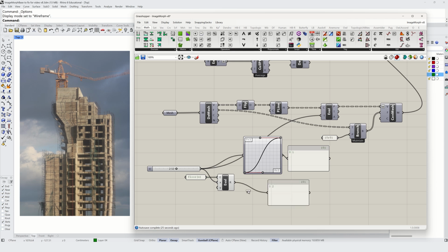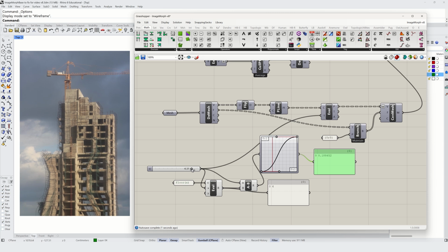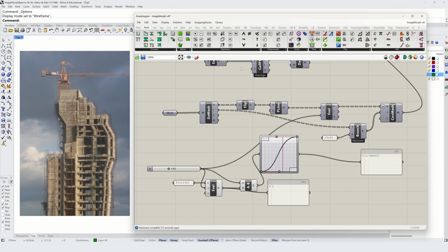Subtract this from the slider to isolate the decimal portion and feed that value into the GraphMapper. Testing the slider shows that the red line now resets back to the left each time the value goes from 0.99 to 0.01. Add the adjusted decimal back onto the whole number portion, and the image will cycle correctly.